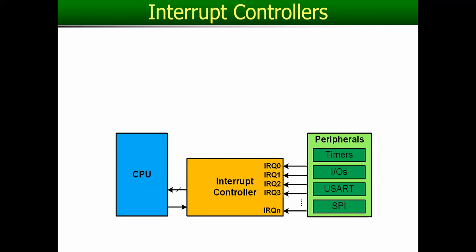All right, and then USART. USART is the Universal Synchronous Asynchronous Receiver Transmitter. It is a chip responsible for serial communication. Let's say a byte of data arrives at the receiver pin of the microcontroller. Instead of the CPU waiting for every bit, it wants the entire byte to arrive and then reads it.